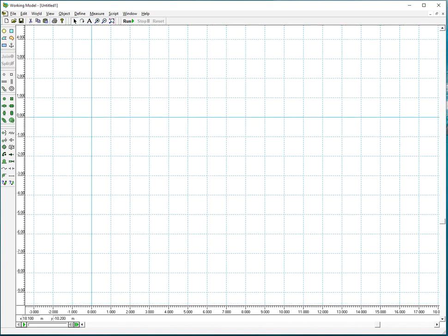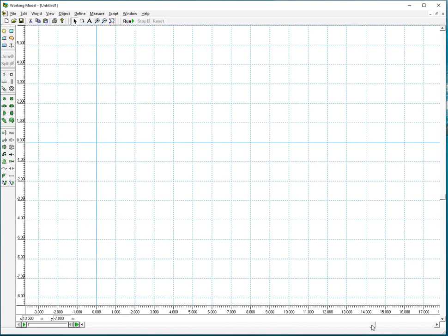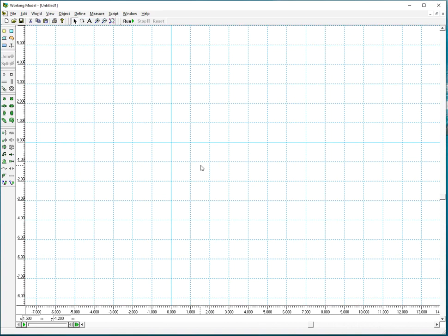This way you can be rigorous and systematic about the location of the bodies relative to the XY plane. So the origin is here, and the x-axis is horizontal to the right. What's shown here, the full screen in white, is the ground link, and you can connect to the ground link as well as bodies between themselves.